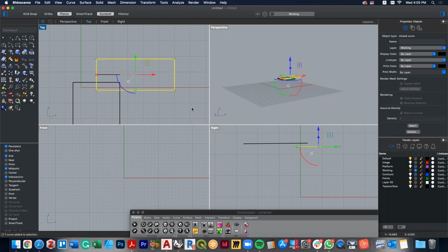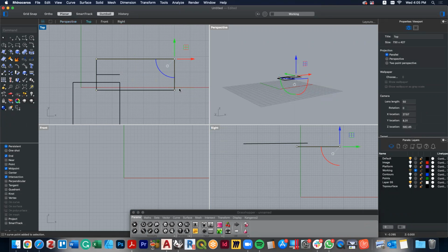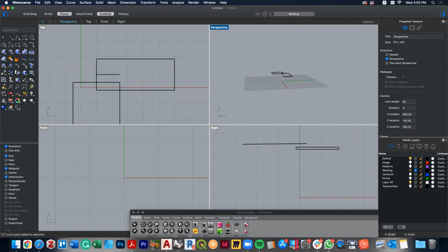And so now what I'm trying to do is I want to move these ends down 1 meter. And so I'm going to select that point again and select that point like I did, and I'm going to go -1. And so that just means that now if we look at it from the side, and let's zoom in and see what we see, you'll see that in actual fact, that plane is down that side there. And so that side is now angling down. That's the grade plane, I call it.